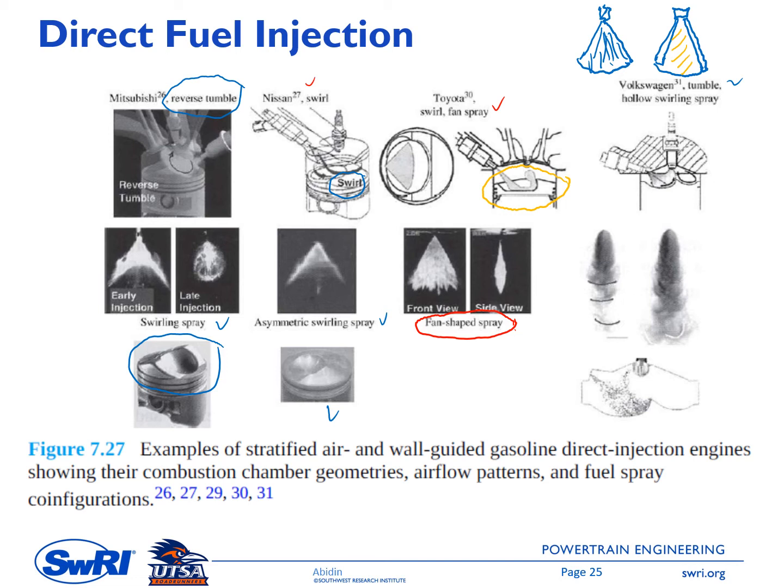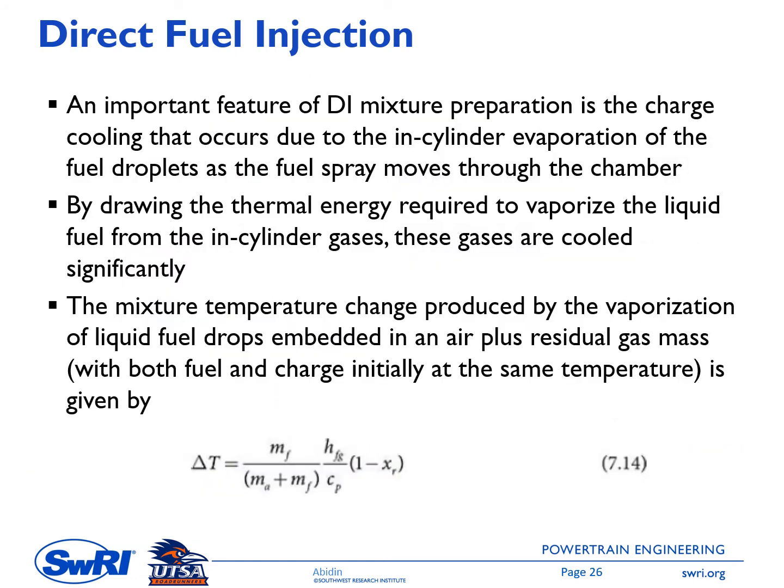So once again, this is showing 4 different engines that utilize a stratified mixture operating condition to improve the engine efficiency. An important feature of DI mixture preparation is the charge cooling that occurs due to the in-cylinder evaporation of the fuel droplets as the fuel spray moves through the chamber.